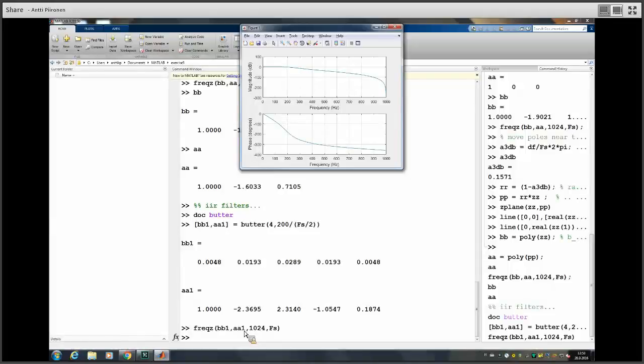Another one is how much stop band attenuation you must have, again application dependent. What is your cutoff frequency? So how to fix now the transition bandwidth, where the stop band begins, you can actually change only one parameter, the order number.